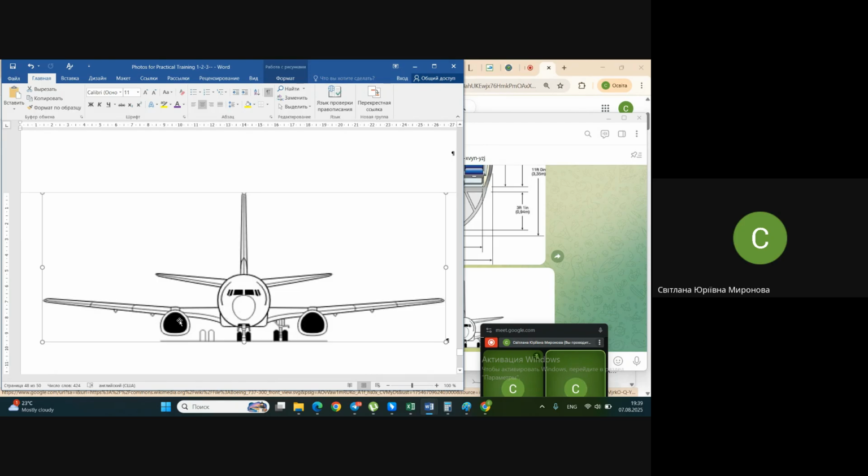But in flight, when you are loaded up, on the contrary, the engine creates a counter moment on the wing and helps you to unload the wing. Due to this, the whole weight of the wing structure more probably may be less than when the engine or some other element of structure is not present there.